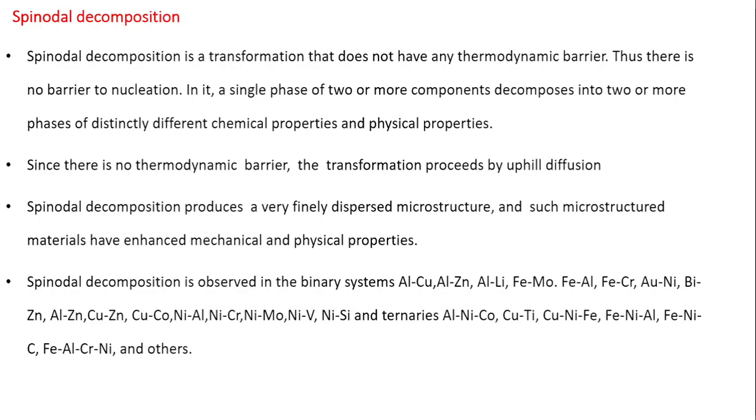Since there is no thermodynamic barrier, the transformation proceeds by uphill diffusion. Spinodal decomposition produces a very finely dispersed microstructure, and such microstructured materials may have enhanced mechanical and physical properties.